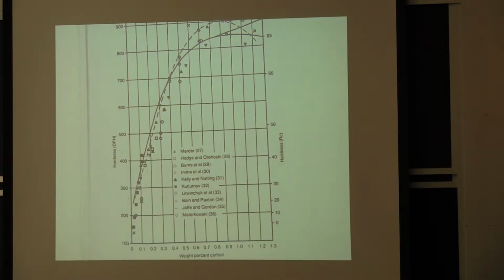And this shows the hardness of the steel. There's hardness and hardenability. Hardness is how hard, in indentation hardness, the steel gets, and it's merely a function of carbon content, and at about 0.6 carbon it tends to level off. But the low carbon steels are not very hardenable.